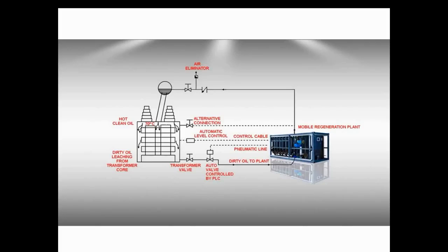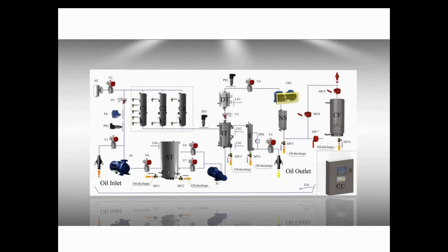Another problem one can meet without regeneration is the disposal of oil. Oil disposal should be done by a licensed waste company. Disposal should be the last oil application, as it has its cost and the oil can further be used in the same or other electrical equipment. We have mentioned today that oil regeneration plants can be stationary.